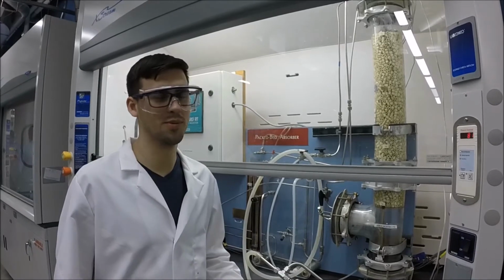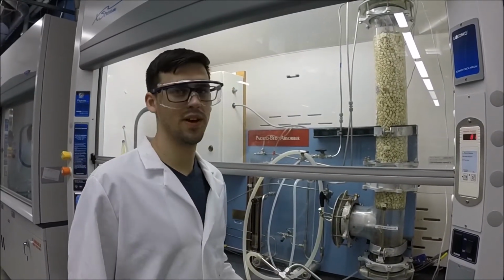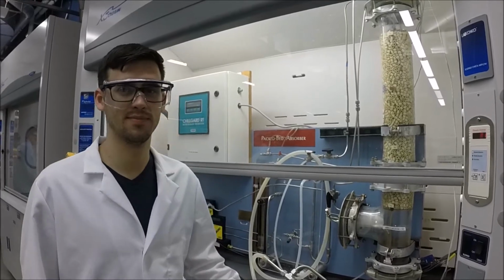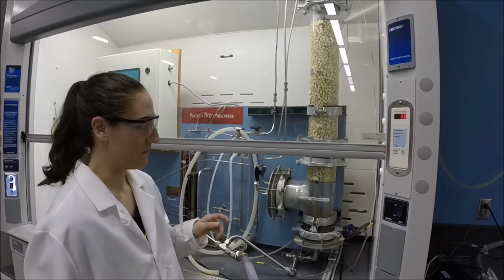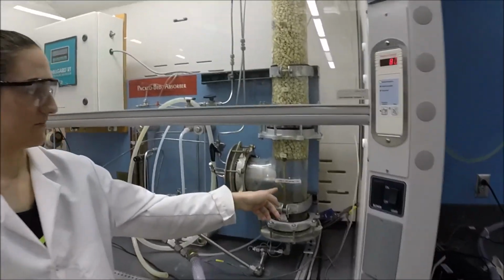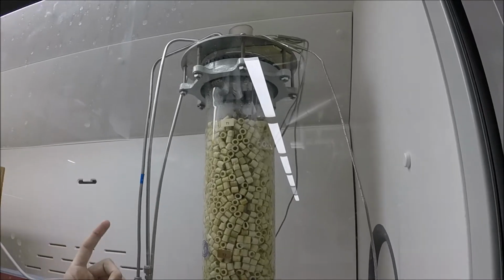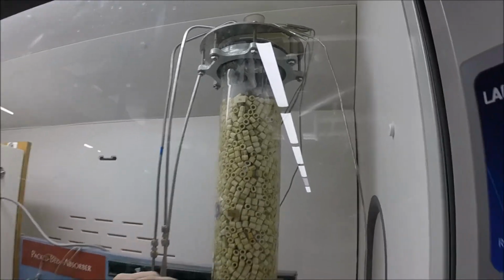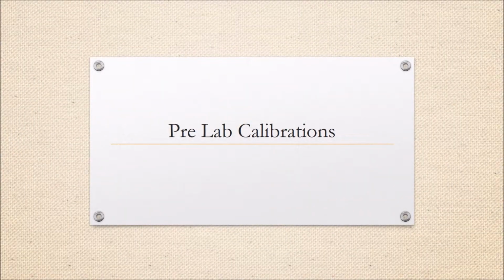There are 4 temperature probes throughout the column, at the bottom and the top, and 2 in the middle, and those values are reported to the LabVIEW software. The inlet of the vapor, or the air, in this apparatus comes in at the bottom of the column. The liquid, which is water, comes in at the top. At the top of the column, there's a liquid distributor to help the liquid fill the entire column instead of just running down the sides.